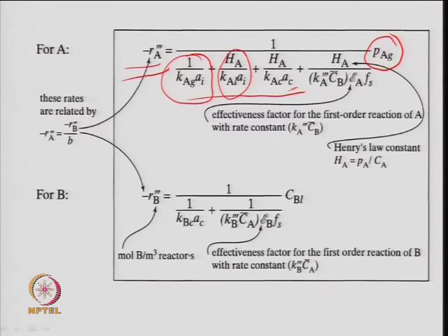Same thing on this side also, if you look at KAG and KAL, they depend again on the size of the gas bubble, and a kind of stirrer design. So, basically it is interfacial area per unit volume. So, small size bubbles you need to have in your reactor if you have a bubble column reactor, right. So, that is the mass transfer coefficient. This will be a function based and can be calculated depending upon the hydrodynamic study.